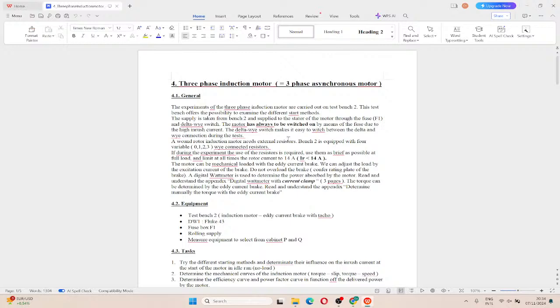Okay. I would say the current graph would just be something like, it's AC, so it's just something like this. So what we need to measure is this, the I_S, that's the first maximum in the first period. Yes. Okay. But how is the device going to catch that moment, the highest moment? I think it mentioned that there is a special mode in Fluke that is designed to catch this. Okay. So we just need to find the mode.